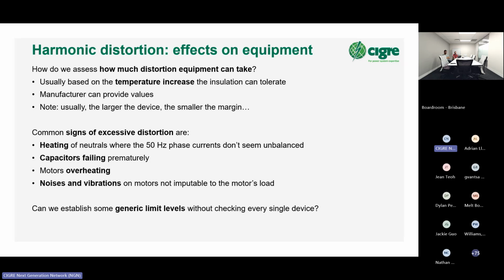So you can mistreat a 500 kVA transformer much more than you can mistreat a 500 MVA transformer. Way more, in proportion to its size. The bigger the machine, the more delicate it is, because given the cost, you cannot oversize things too much. So everything is built on tight margins. You get out of those margins and you are done. So that is in general the thing.